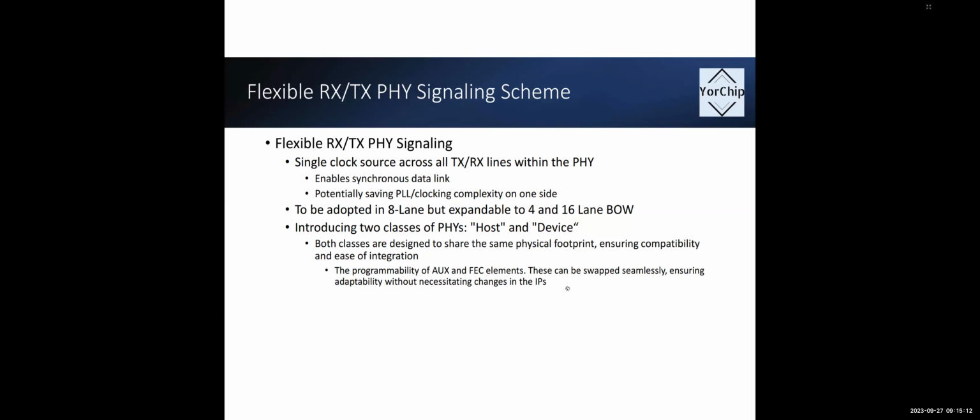Right. It makes sense. Now just as a complete side question, if this is mostly focused on the lower speeds and lowering costs, the other way you can handle this is just to have simple ring oscillators on each side, and you make it async. I suppose if you're trying to get very low latency, then that's the primary reason you might not want to do that. But from a specking perspective, that's another way you can go about it.